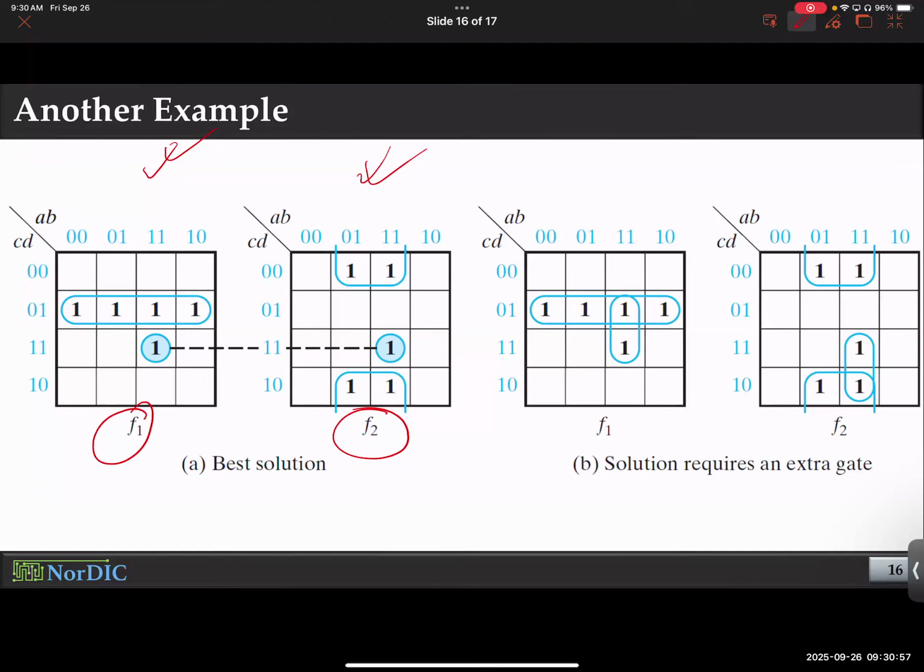Now, if we just go for general grouping, let's start with the ones that we would typically do, folks. We learned when we went through K-maps, and I told you myself: if you see a 1 sitting alone somewhere, bring it inside a group. Don't let it sit alone, because that will optimize the overall output. Did I tell you that? Okay, so this is our approach.